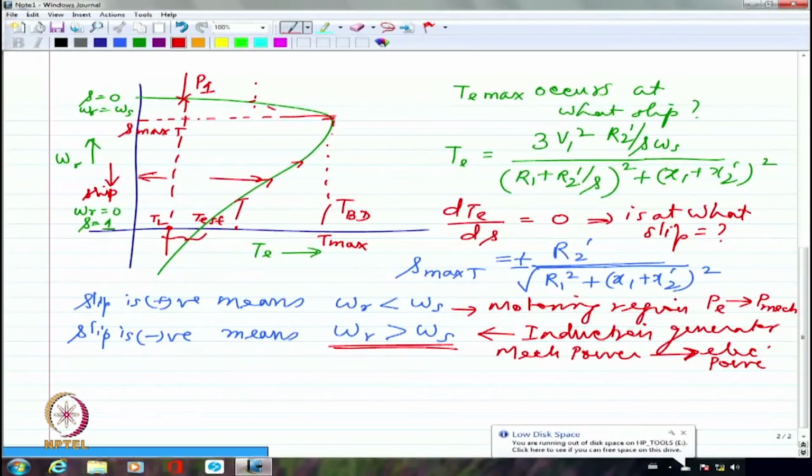It will just stall. It will say overload and wait. The elevator definitely will have an indicative button that it is overload, because the load torque is greater than whatever the machine is capable of generating at the starting condition. So that's a very good question, very valid question.